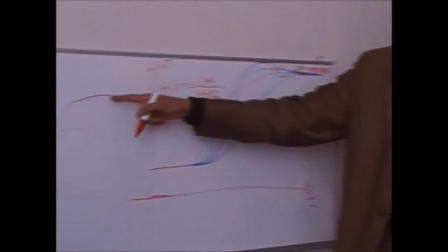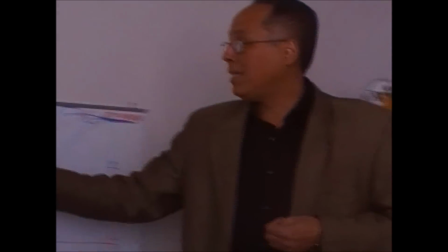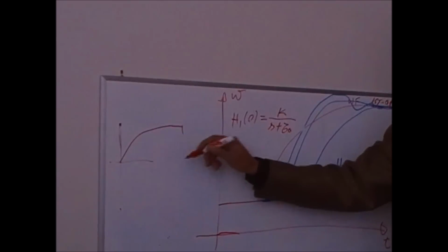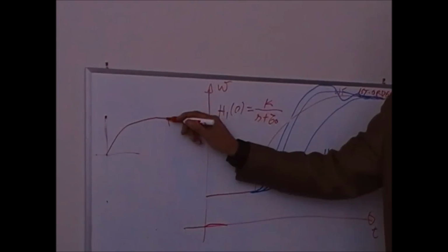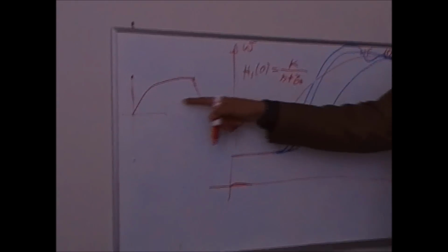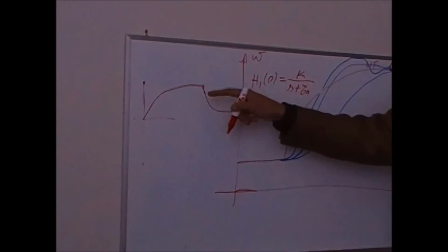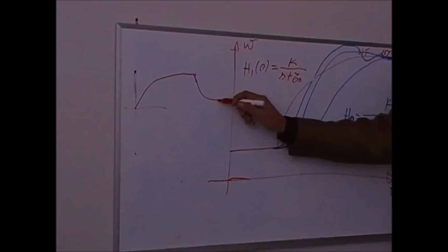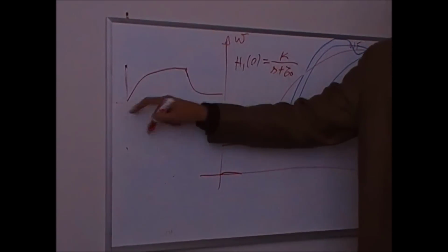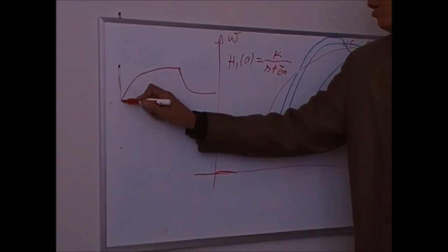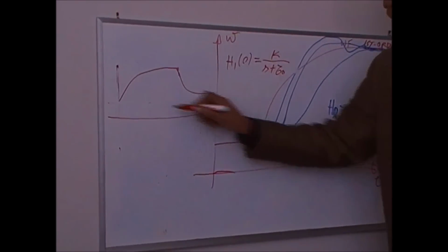You're going to use the visualization tool to measure the speed and store it to be used later in a spreadsheet, in Excel or something else. In the second part of the experiment, you're going to reduce the voltage for the motor to go down. The same thing is going to happen. If I reduce the voltage, the speed is going to go down and stabilize somewhere.